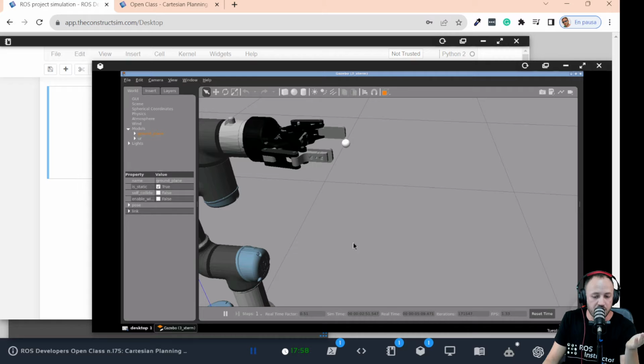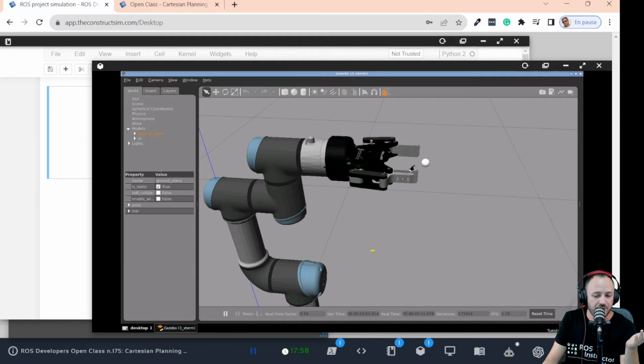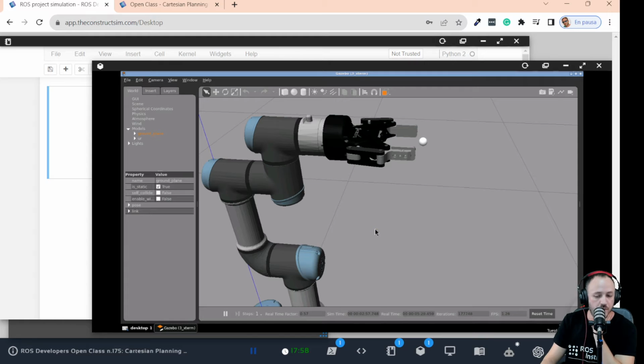So imagine that this arm and this gripper has to pick a cup of coffee, yeah? In order to move it from one place to another, yeah? In that case, I want the cup to remain vertical at every moment through the trajectory, right? Because otherwise the coffee would be spilled out of the cup, yeah? So for these kinds of trajectories where you want to have control at every moment over your end effector and the gripper, for these cases you would use Cartesian paths. Yeah?